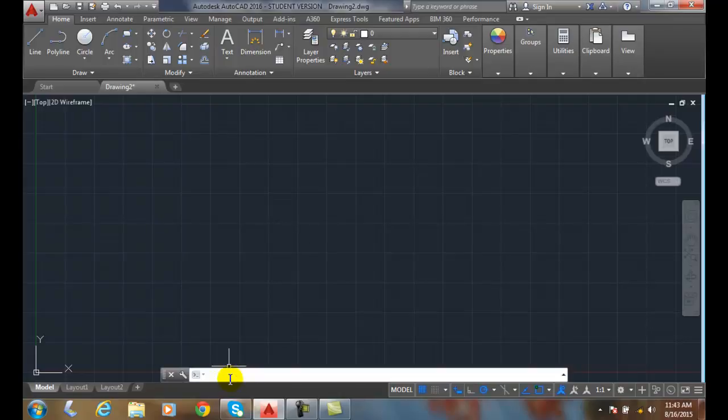So typically I tell students, I want you to make the limits a little bigger than you're going to need. So I use 0, 0. I'll type it in this time, and I just use 200 by 200 for mechanical parts. That means it's 200 inches by 200 inches. Generally you're not going to make anything bigger than that, and you can just draw on it. What this helps AutoCAD do is it helps it in things like the zoom and plot command, and it also helps on the calculations. Behind the scenes, it's just a big database doing math, and it helps prevent calculation errors, rounding errors.